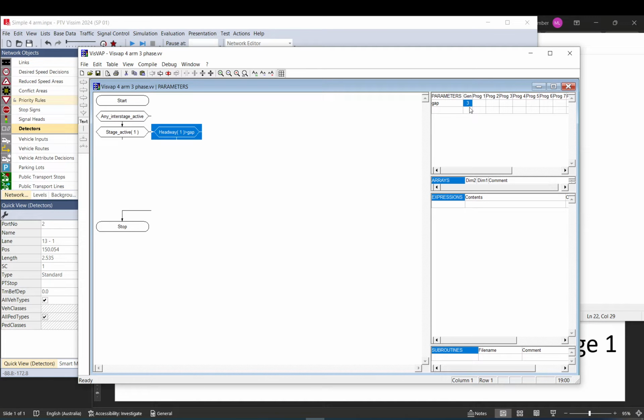If the following time is less than 3 seconds, vehicles usually drive quite close to each other. If it's more than 3 seconds, I think it's safe to say that the demand is not that great. They don't squeeze and push each other that much if it's greater than that. So if the headway is greater than gap, that means there is no demand. What we can do,